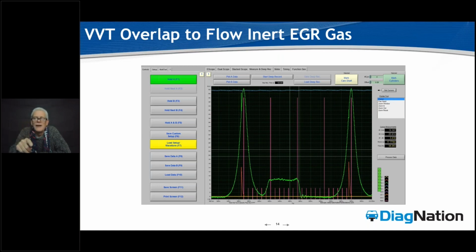Man, you'll drive yourself nuts looking for sensor problems with that mass plausibility code, and it's a dirty intake. We can see it here, right? This is, to me, passionate stuff. We've got to get guys in the habit of using this stage 2, step 2, to go after these deposit-related problems, the leakages, the hard stuff that we can't find.